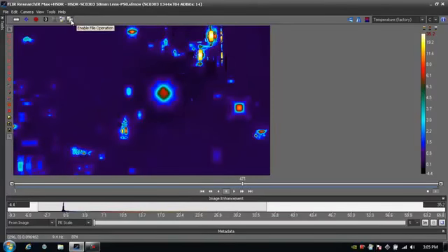The other really nice thing about image subtraction is it helps your eyeball visually pick out small, more subtle temperature differences that you may not notice when you're not applying image subtraction. It's a really great tool for being able to pull out small temperature differences and help dealing with devices that have varying emissivities or apparent reflected temperature differences.